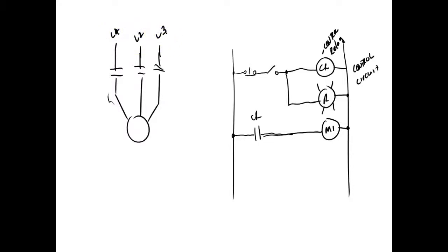And that's the problem we get into: we call this L1 and L2, but this L1 and L2 over here might be 26 volts AC. This over here could be 660 volts AC. And if you get this L1 confused with that L1, you're going to burn some stuff up. So you've got to be real careful of that.